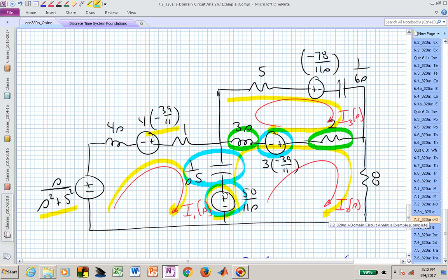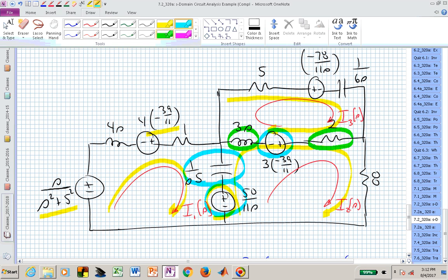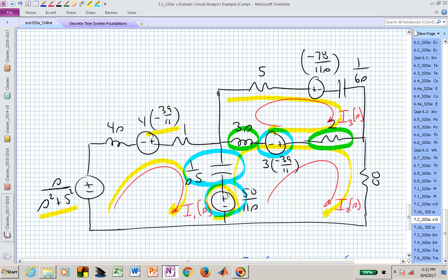Finally, then, dealing with the sources associated with I sub 3, now we have this source due to capacitor 1 and this source due to inductor 2. Let's look at capacitor 1's voltage source. If we increased that, that's going to go against I sub 3, so that needs to be introduced with a negative sign. The inductor's voltage source, if we increase that, that likewise will serve to impede I sub 3. Both of those terms now algebraically need to enter with a negative sign.